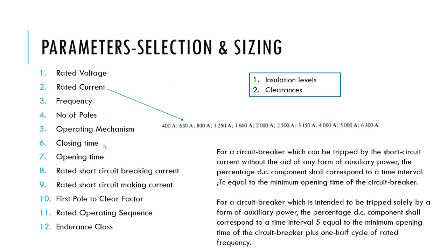So the next one is closing time and the opening time. So closing time, it's obvious it should be less than 120 milliseconds. Generally, we recommend 100 milliseconds. Less than 100 milliseconds is the closing time. Opening time should be less than 60 milliseconds. These are some standards in IEEE, IS 13118, and these are some practice.